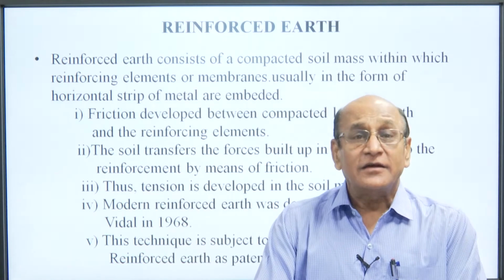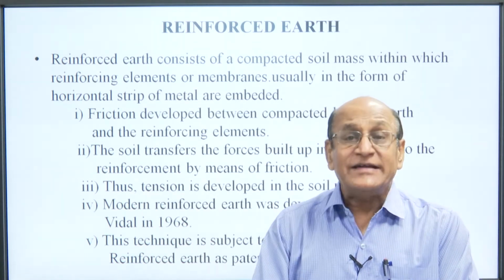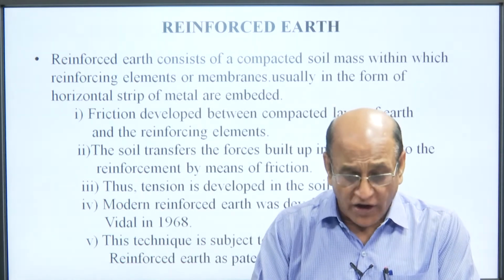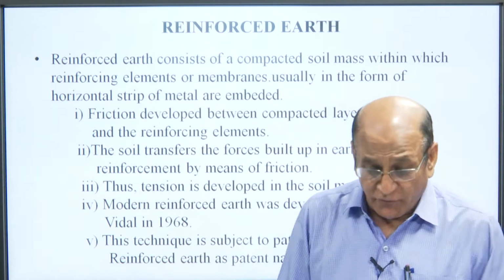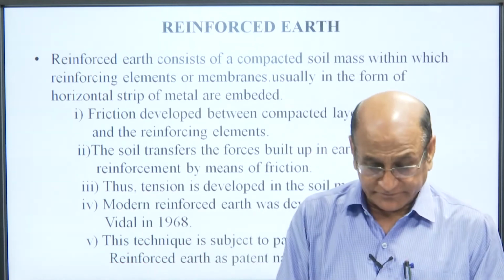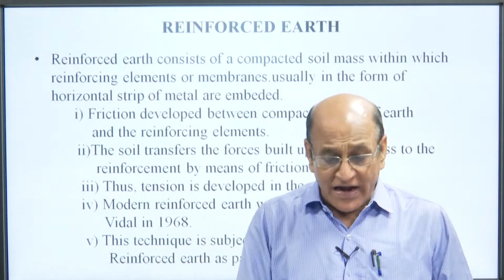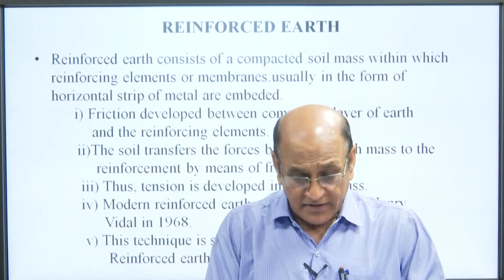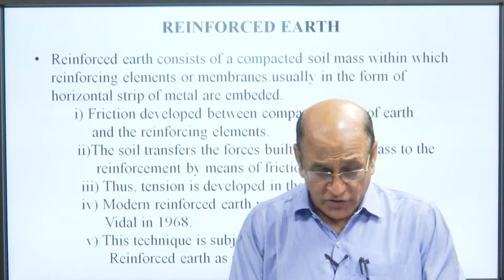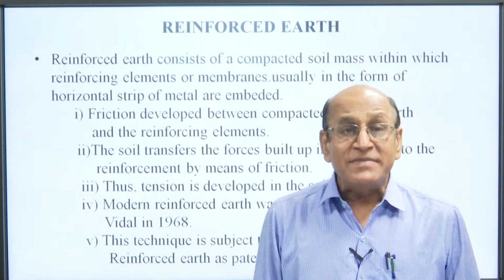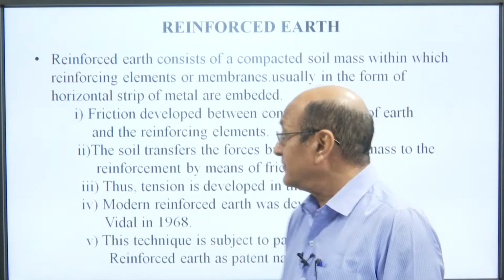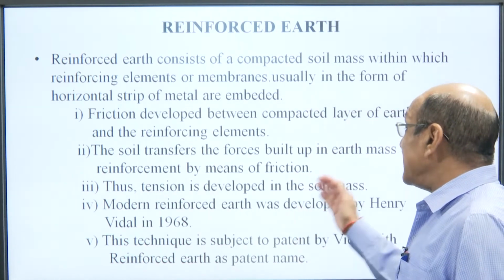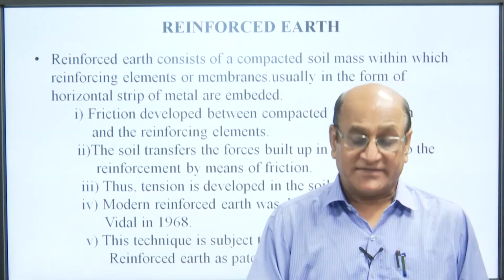The first is friction developed between compacted layer of earth and reinforcing elements. The soil transfers the forces built up in earth mass to the reinforcement by means of friction. Thus, the tension is developed in the soil mass.